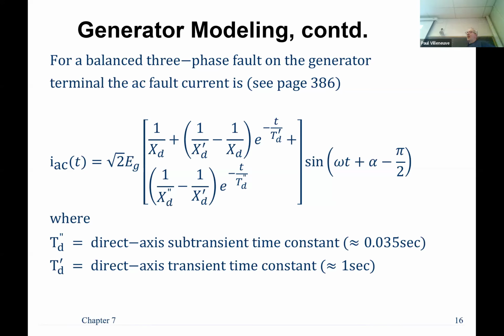But more often than not, your breakers and your machine have to be able to withstand the amount of current that's available during the subtransient time and interrupt during the transient time. And that's getting more and more challenging, because what we're learning with the power system is if we can isolate faults faster, not only do we have less equipment damage, but we actually have a more reliable system. Because if you keep a fault on too long, you can actually trip off other parts of the system because everybody gets out of sync.